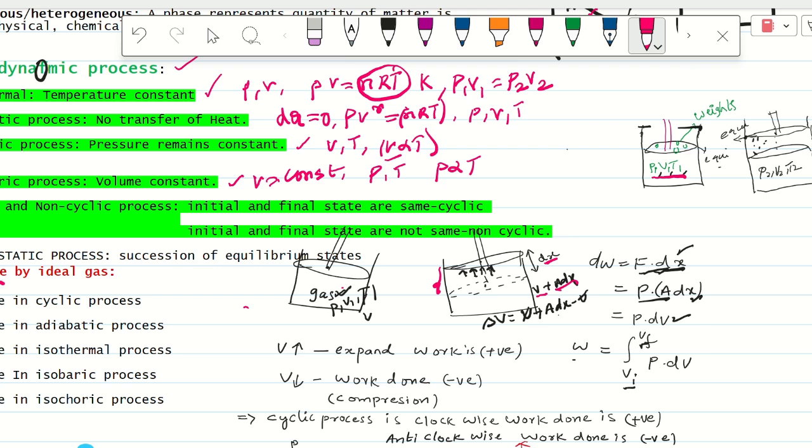That also can be possible. If not, this is a closed vessel, and only the movable piston moves up and down. In that case, the piston will oscillate up and down when changes happen suddenly. But if you remove weights slowly, then after each change it gets to equilibrium. So that is explaining the quasi-static process.